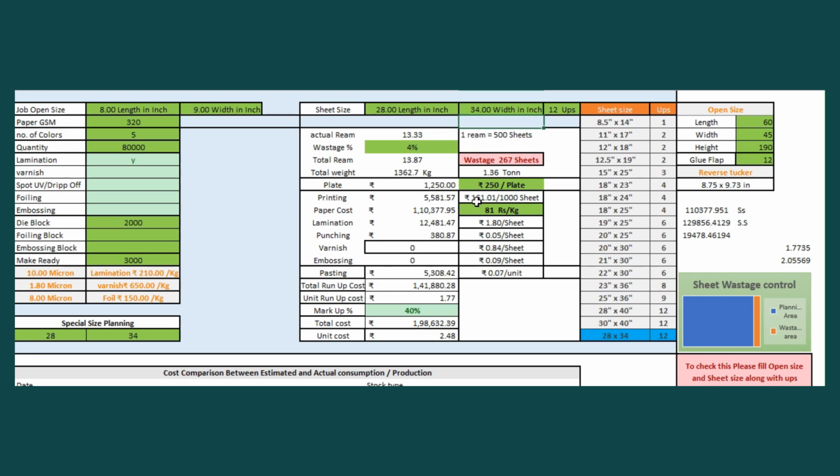Ideally, the ink consumption of offset depends on the stock or the substrate, what exactly the porosity of the substrate is. It will consume ink as per the porous nature of the substrate. The higher the porosity, the higher the ink micron or ink thickness consumed. After observing different substrates, the ideal range of ink thickness is between 1.5 to 2 micron.